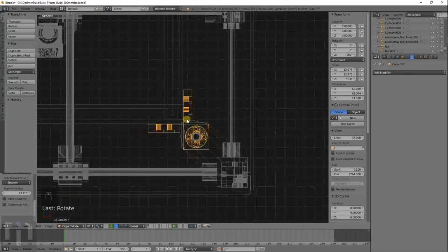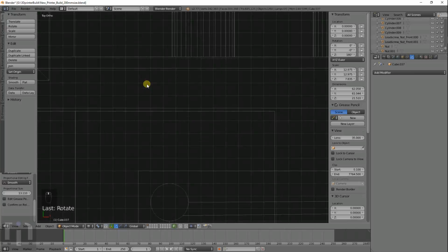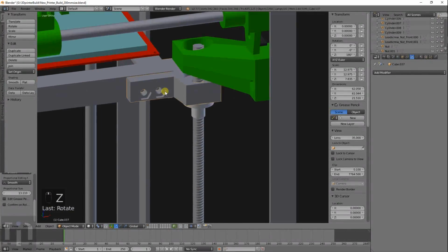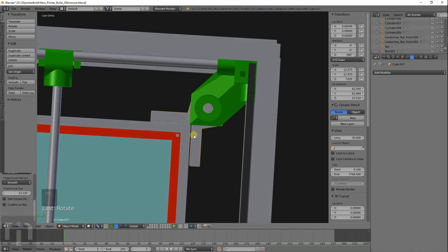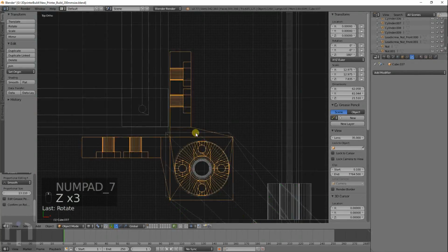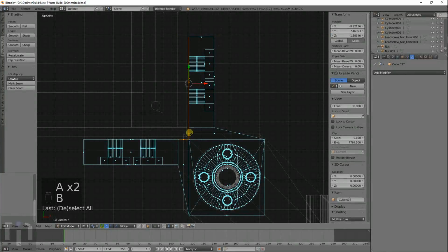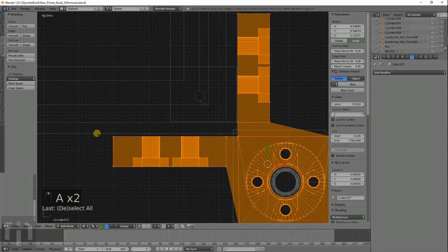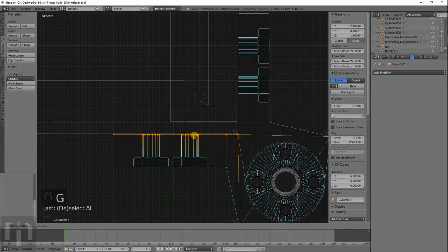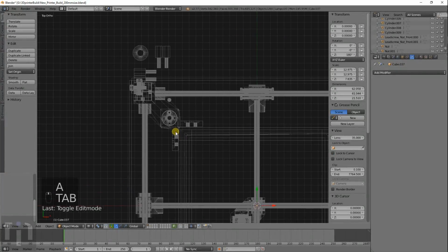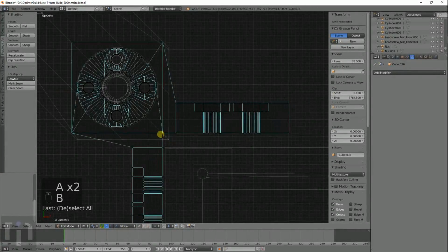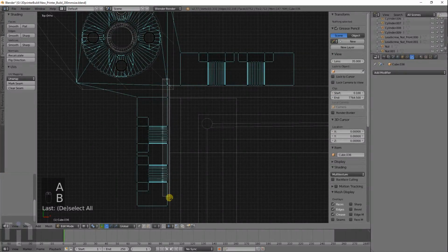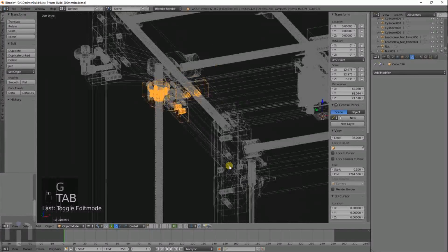I just noticed that I got a gap of about 1 millimeter there. Do I have that over here too? I do, but that's okay though. What you can do to fix that is just select all these. Go to vertex mode first. Move it in a little bit. Alright, fixes that. And do the same over here. See, sometimes you don't catch things like this until it's too late, but got this one in time. There we go. Those are both fixed.